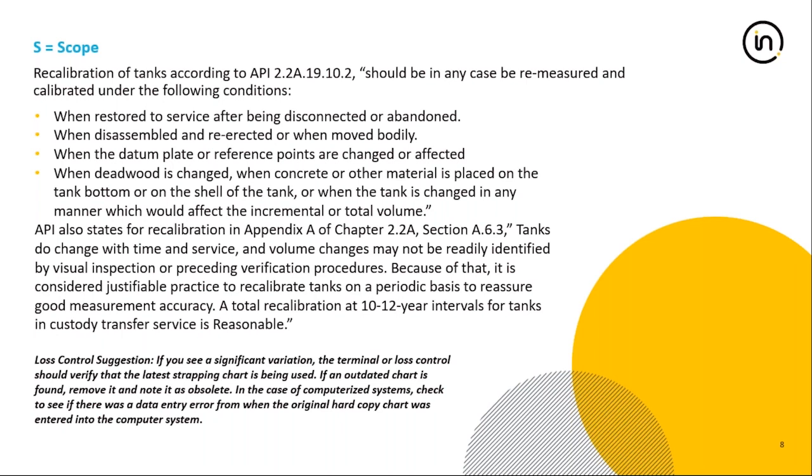Maybe you are going to remove some heating coils, maybe you are going to add some baffles, maybe you are going to add a mixer. Whatever you are going to do with the tank, if it affects the actual volume, it's going to affect your tank calibration. So then you should redo the whole calibration for the tank.